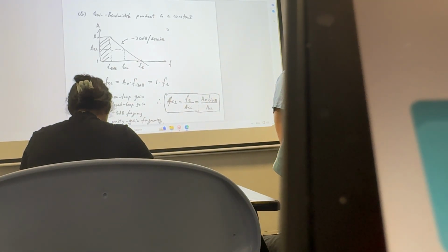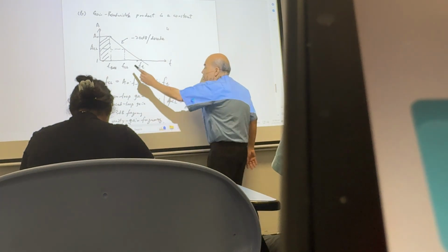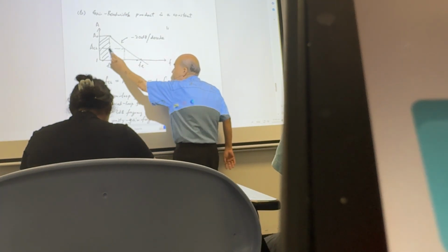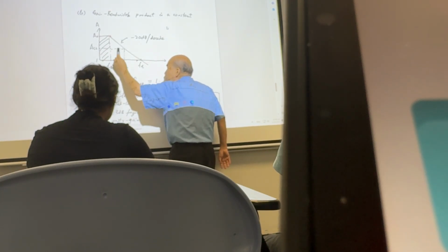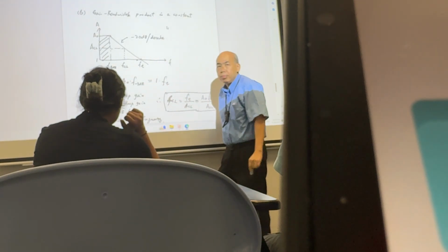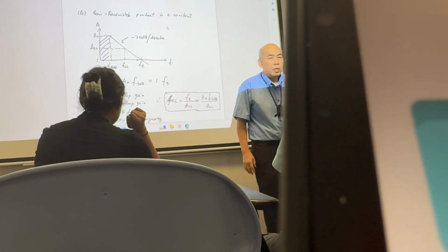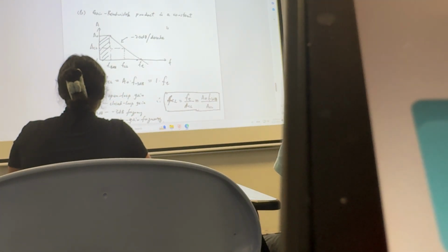Now the area under this diagram is the same. You look at the area in here, the dotted line will be equal to the area in here, and also the area at the intercept point between this and this. So you can say it is a constant area. In the limit it is 1 times Ft. So the op-amp characteristic is a one-pole system. Gain bandwidth product is a constant. This is an important property you need to know.